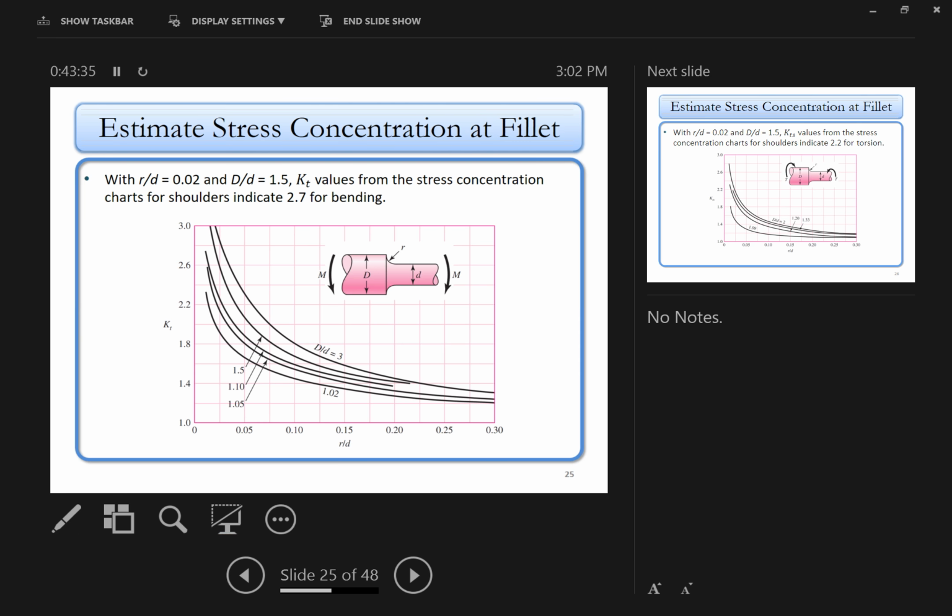If you want to calculate the minimum shaft diameter, which I will show you a formula for in the handout that you also have, you can calculate this minimum shaft diameter, but you do need the stress concentration factor right here. So what we do now is you have to start somewhere, right? That somewhere basically is an estimated or conservative value that you should use from the beginning. Not the final value it's going to be, but some value that you have to start with.